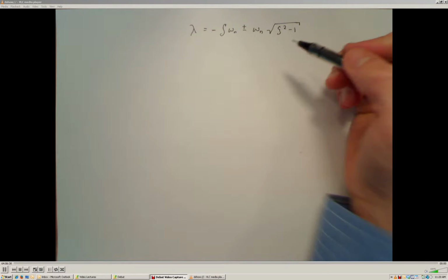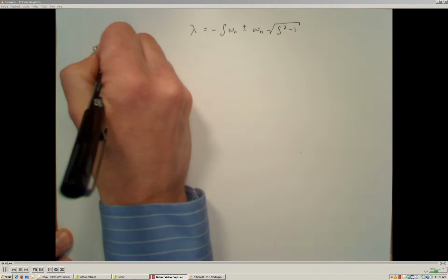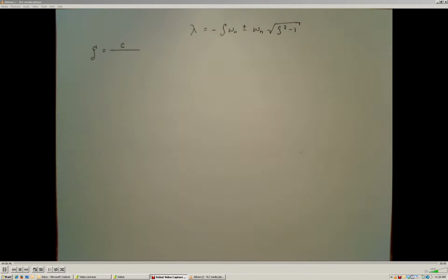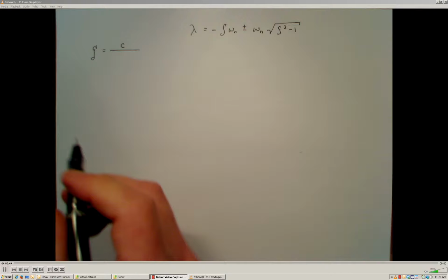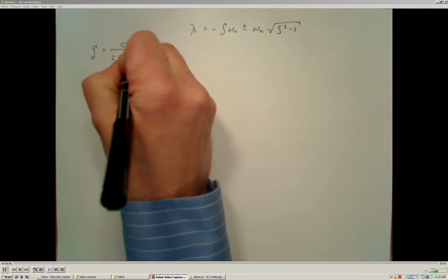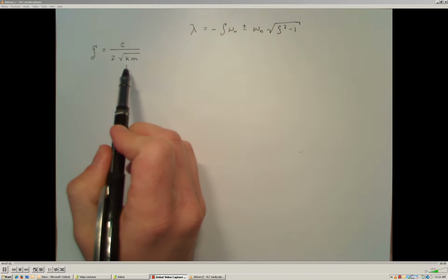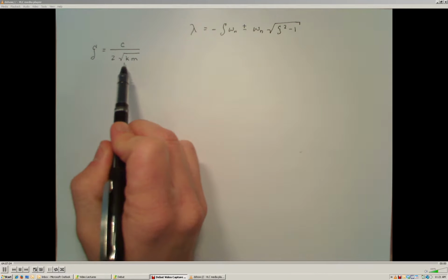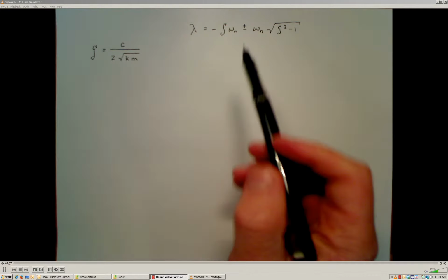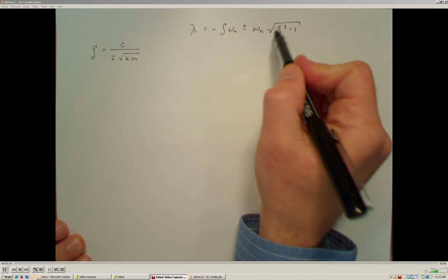Remember that the damping ratio is given by the damping of the system divided by 2 times the square root of the stiffness times the inertia of the system. Right, so if we can come up with our general second-order differential equation and determine what the values of the inertia, the stiffness, and the damping are, we can calculate the value of the damping ratio. So we have 3 possible cases that we need to be worried about with the damping ratio. And it all involves this term under the radical right here.